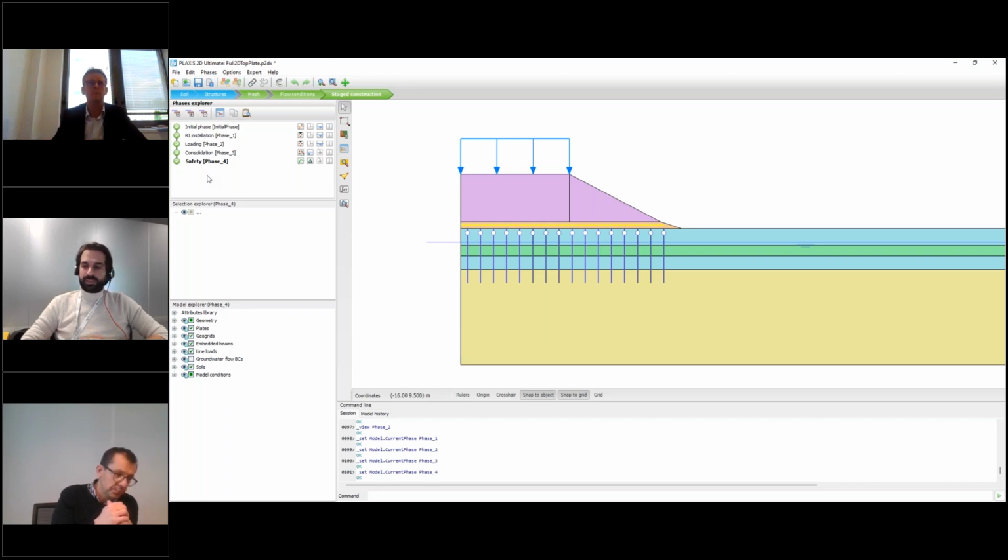Great. There is another question: how can we connect the rigid inclusion to the load transfer platform? Well, that's exactly what I've just been presenting. Two possibilities. The first one simply consists of introducing a small extension of the rigid inclusion inside the mattress, which is completely fictitious, doesn't exist, and providing a skin resistance along that small extension such that its integration with the length of that extension provides the amount of force you'd like to be transmitted. That's method one. And the second one is to add this dummy plate.